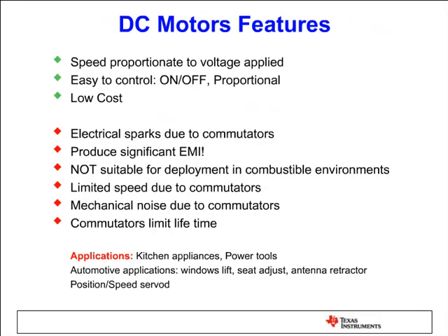Previously, brush DC motors were used very commonly, but today most people are replacing them with BLDC type of motors or PMSM type of motors. Although it's easy to control brush DC motors, and they're cheap, the brushes cause some issues like electrical spark, EMI problems, audible noise, and you need to, of course, maintain the brushes and replace them periodically. And you cannot go to higher speeds, so that's why DC motors are becoming less and less popular nowadays.